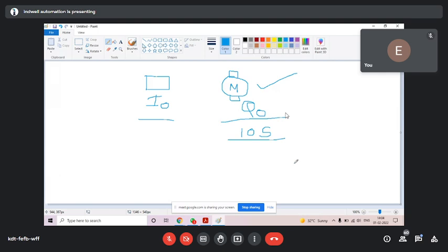Vaishali, you modified, but you see, you have taken NC and Q0. If you have given direct NC to Q0, what will happen as you run without pressing the switch? Q0 will be on. You can see without pressing the switch, Q0 is getting on. Tanis, not correct. You people understand, but you are confused how to put that in the ladder. See, Siddharth, you did the same.